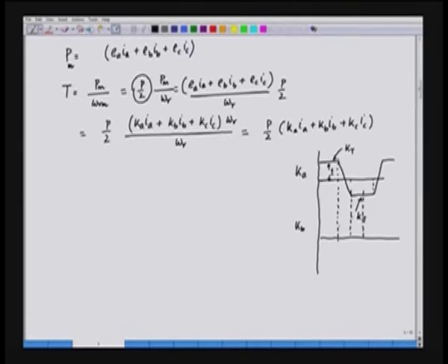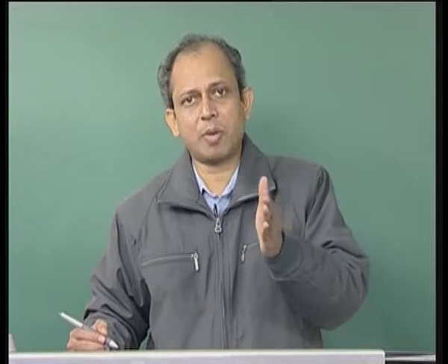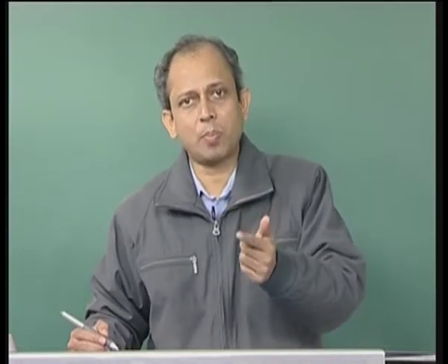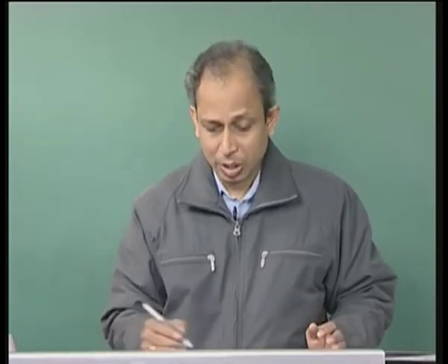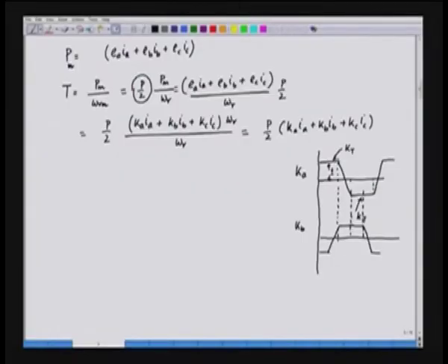So, this is the nature of Kb and so on, and similarly we can have Kc. Kc will be again shifted from Kb by 120. So, we have the functions for phase A, phase B and phase C. When the respective functions are multiplied with the corresponding current, we get the torque, and the torque in this case is Ka plus Kb plus Kc into P by 2, and omega gets cancelled. So, this is the expression for the torque.